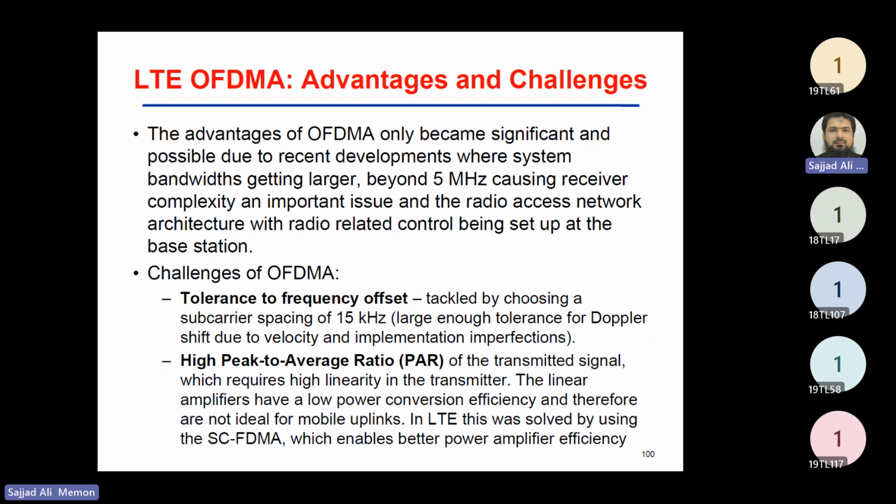That will force the HPA into saturation operation, where it will be clipping the excessive voltage that is not in the operative range of the high power amplifier. So that will be a loss of information if we have this PAPR occurrence.